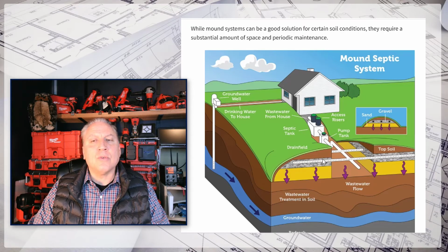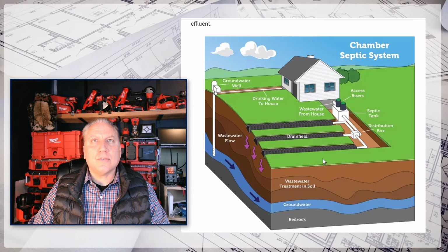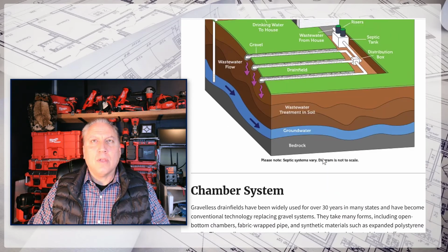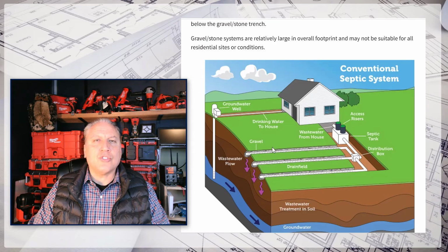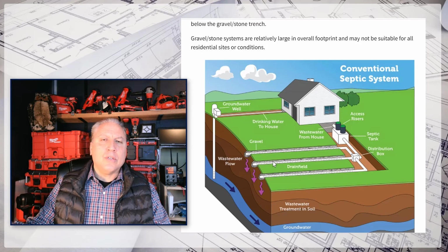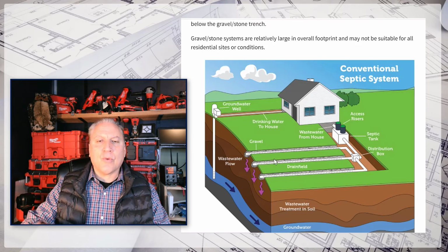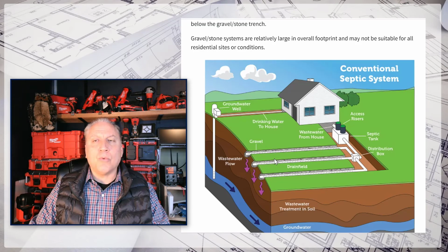In fact, when you are digging these trenches for your drain field, you have to dig when it's dry, because the sides of these trenches also have to be loose and crumbly. If you dig the trenches when it's raining, or it rains afterwards and the sides get slick, that can create a coating of mud that will dry and prevent the drainage from going into this trench properly.